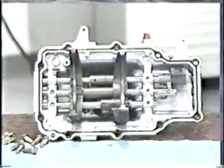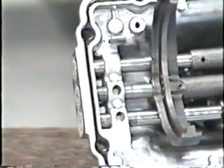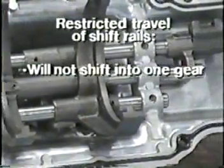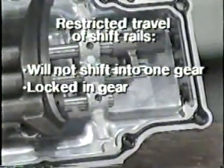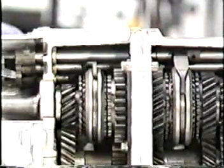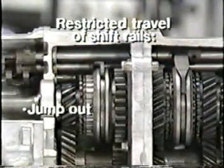Shift rails can have a variety of things go wrong, resulting in different kinds of shift concerns. Loose or improperly installed parts can restrict shift rail travel and cause a transmission to not shift into one particular gear or to lock into one gear and not shift at all. Restricted travel can also prevent the synchronizer from fully engaging a gear and create jump-out problems.